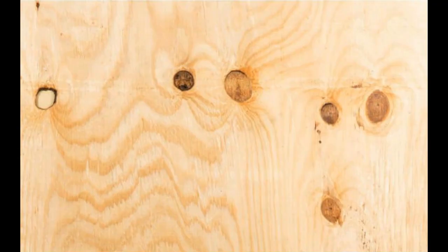C has knot holes up to 1 inch, and occasionally knot holes 1/2 inch larger are permitted, providing the total width of all knots within a specified section does not exceed certain limits. Limited splits are permitted, and it is the minimum veneer permitted in exterior type plywoods. D permits knots 2.5 inches or larger under certain specified limits, and limited splits are permitted. Obviously, as you go down in grades, the overall finish is a lot rougher.